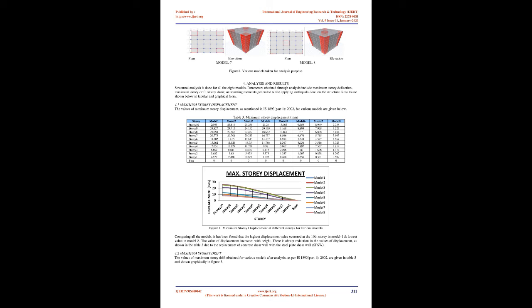2.1 Steps for analysis and design of structural elements. 1. We choose Indian code for design. In ETABS, file new model, use built-in settings with set display unit, steel design code, concrete code, section database. 2. Selection of grid plan. Number of grid lines in X and Y direction are 5. Spacing in X and Y direction is 5 m. Number of stories in building is 10. Height of typical story and bottom story is 3 m.